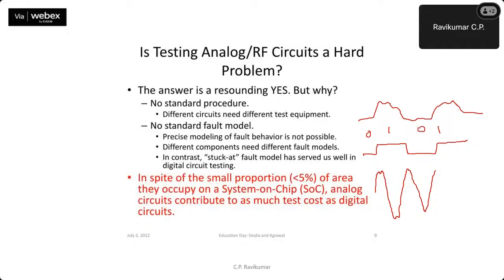but once the structural faults pass and we have parametric faults, like maybe the frequency that we were supposed to get is 10 megahertz, but maybe we are getting slightly higher or slightly lower, right? And there may be a specification which says that the oscillator frequency should be 10 megahertz plus or minus 10%.